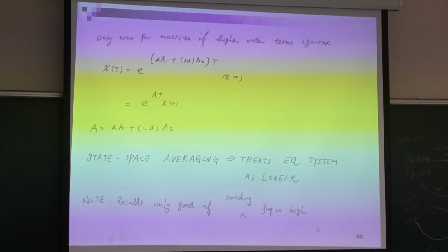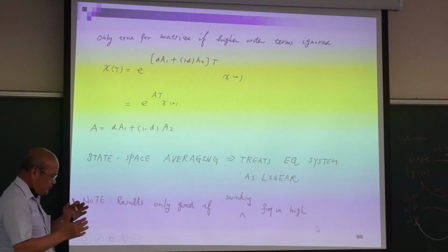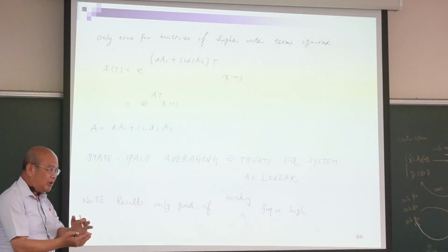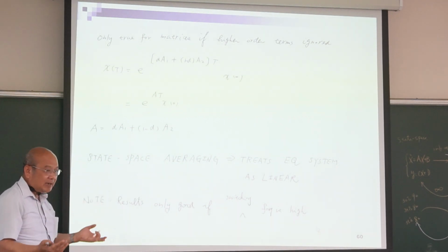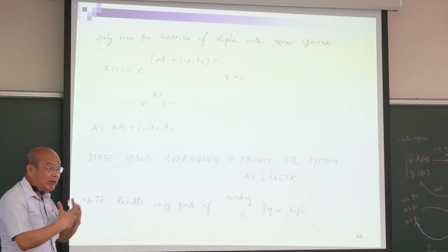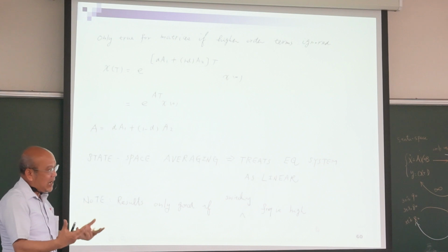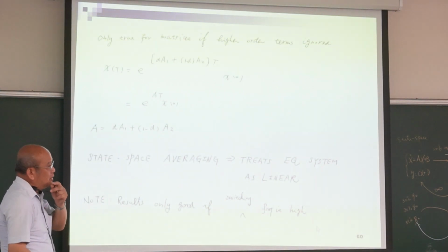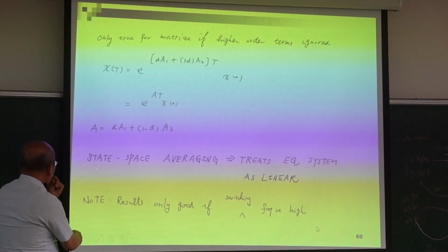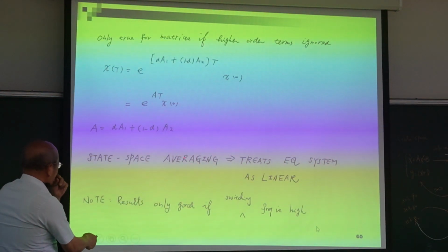So in last class, we discussed state space averaging. So what is state space averaging? Because we have switching. One is Q on, D off. Another is Q off, D on. So we have different mathematical models. But to design the controller, we only have one controller. So we have to combine the two models into one. How can we combine two models into one? We can use state space averaging.